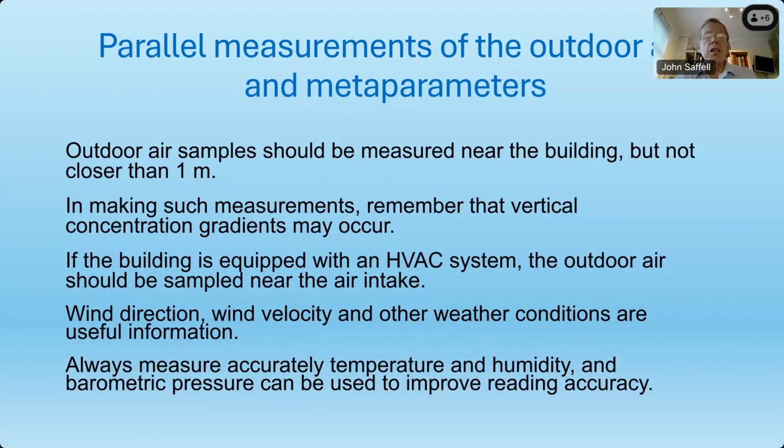Now, Biane reminded us that we need to measure indoor versus outdoor, and it's always the difference that matters, and so does Andy, and I agree, it's a delta CO2 concentration, not the absolute. And if you're in a rural area, you can make an assumption of 425 ppm, which I believe is Hawaii's number this year, and next year it'll be 427. But you should always measure the outdoor air, because in cities, as we just saw in Copenhagen, it can be much higher.